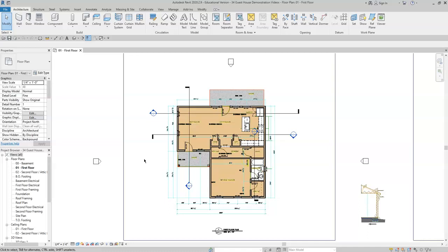Continuing with our Revit model, once we have completed all of our finishes, we will do our last piece of finish work and complete our lighting. Now lighting requires a few more elements added before we can insert lights. We'll need to cut a section view through the house and go ahead and open that section view. I'm going to choose this one here.